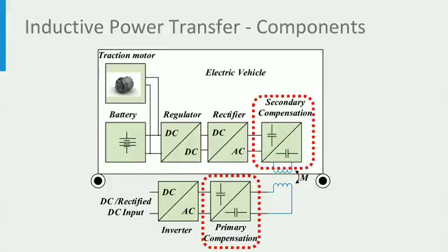The inverter pulse modulation voltage creates a high-frequency sinusoidal AC current and voltage in the base pad by means of resonance with a compensation circuit consisting of capacitors. The sinusoidal AC power from the primary coil is transferred to the secondary coil due to the electromagnetic coupling.